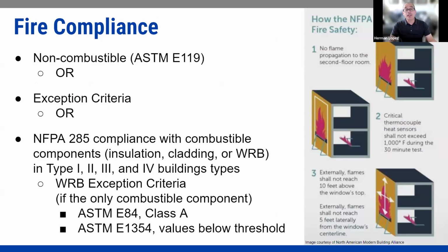Yeah, so NFPA 285, very quickly. NFPA 285, for a lot of us, it's about as clear as mud, even on the best day. Understanding what it is, it's not a product test, it's an assembly test. So if somebody holds up a product and says, we're NFPA 285 certified, no, that's not the complete truth. What we're looking at is assembly tests. The three triggers there are the plastic foam insulation, the weather barrier, and the exterior cladding.